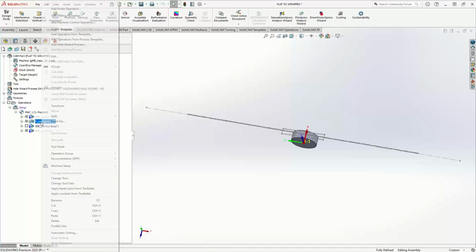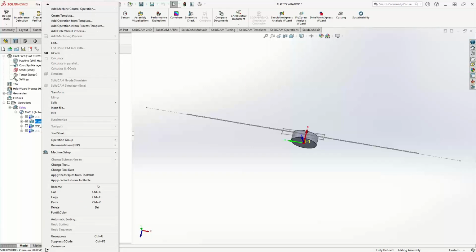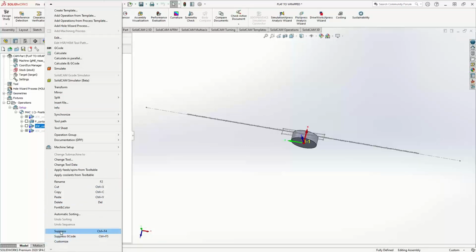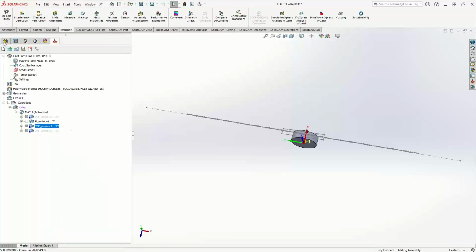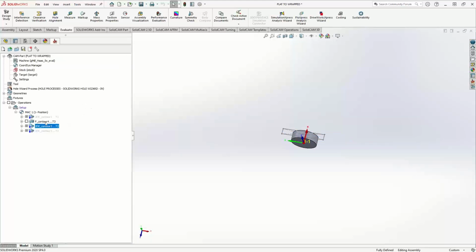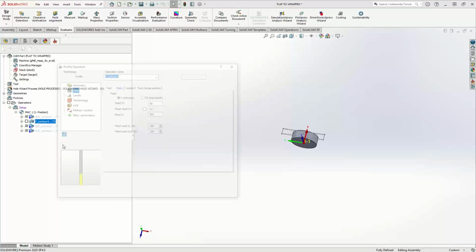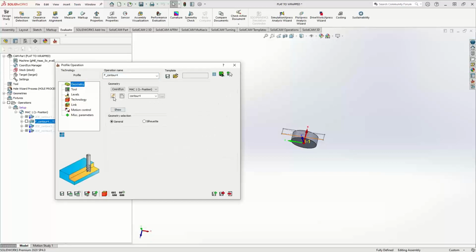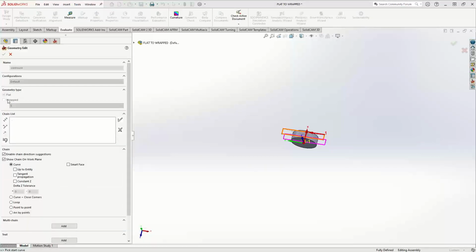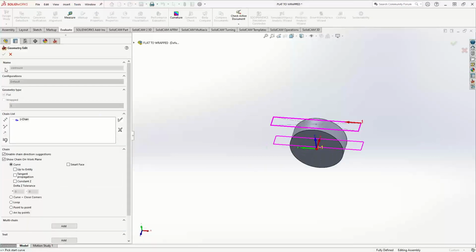The only other thing left on this part that I want to show that I didn't know we actually could do, but we can, is again the idea that if you have a pocket or a profile toolpath, all those options are open to you. Even though it's wrapped, you can still do a bunch of stuff that a wrapped toolpath would do. Like for instance, you see on screen that I have that square. I'm wrapping that square around the x-axis, but I'm doing so as flat geometry.